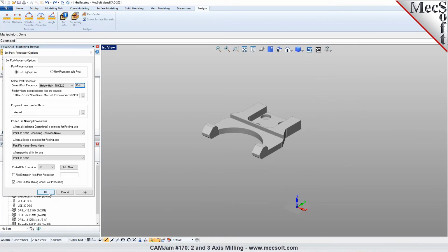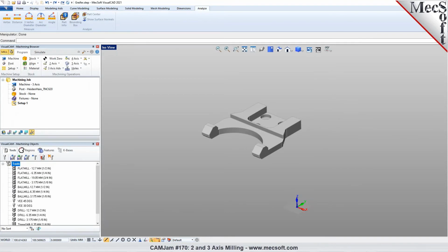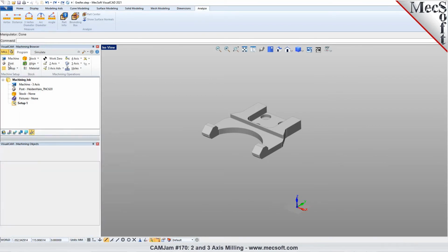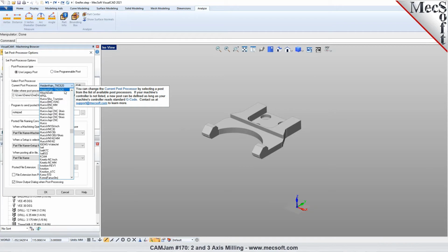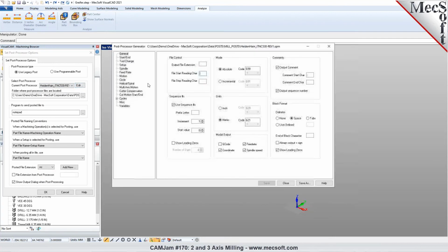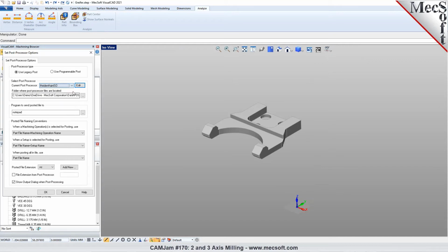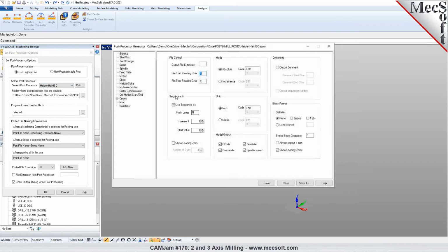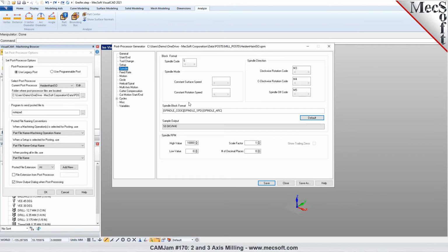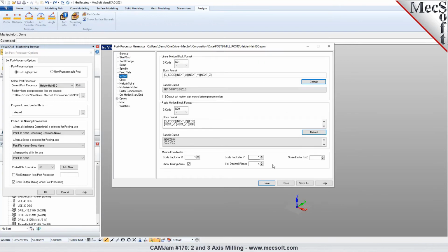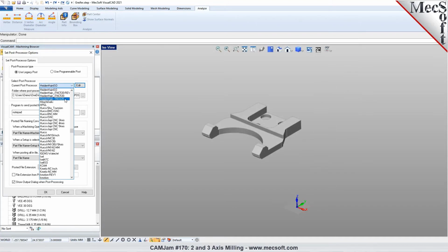Is the post processor generating ISO code, or is it the HEIDENHAIN language? Right now, this one, the TNC 620, looks like it's the HEIDENHAIN language, but we do have an ISO code post processor as well. Here, these are all HEIDENHAIN formats. We have a generic ISO format in here, which can output in G0 and G1 format, as you can see. So it can be set up for either one. We can have different posts, one for each. This particular one uses the ISO for the HEIDENHAIN format, the one that you're looking at.